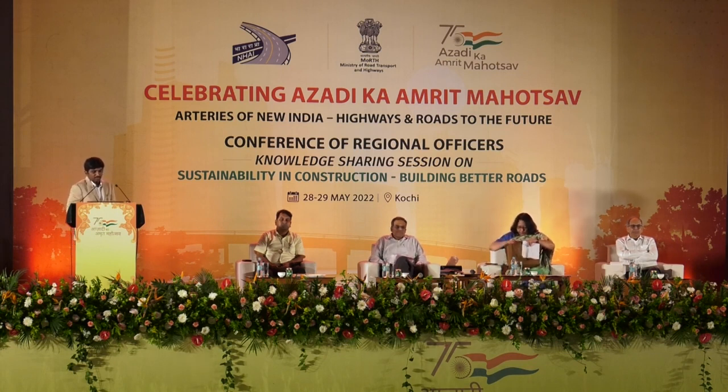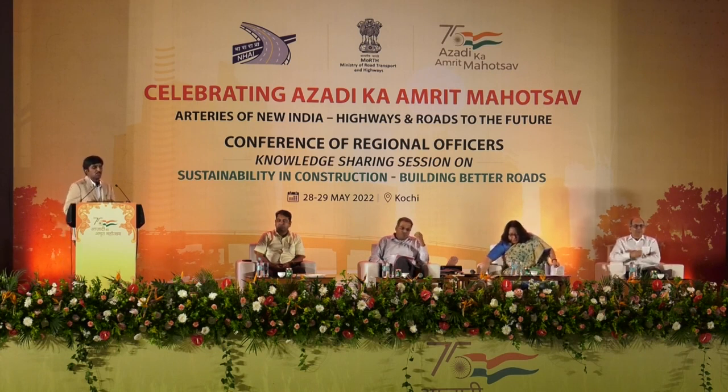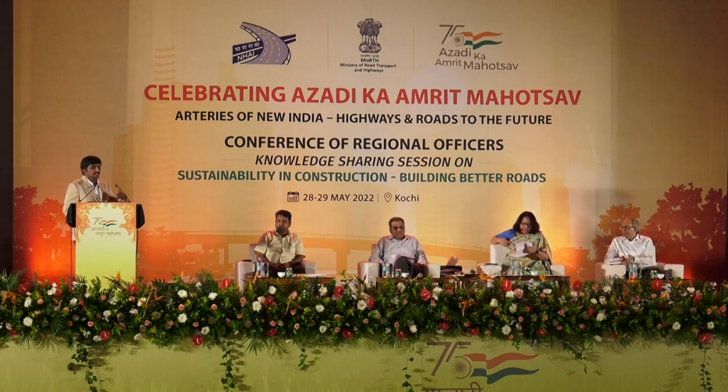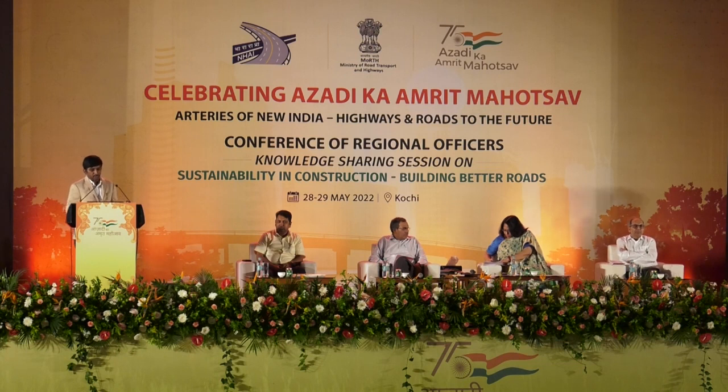So this is an ongoing work. The package at Andaman, the work is presently going on. We submitted the mix design. Based on that, we went to site and checked the distress levels. Based on distress levels and traffic, we considered how much depth we have to recycle and how much amount of cement is required. The work is presently going on.